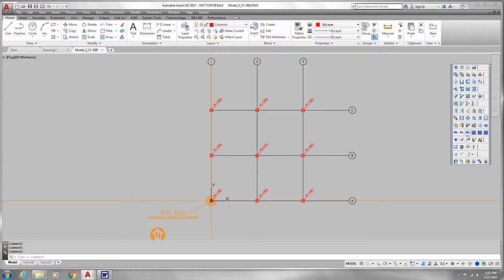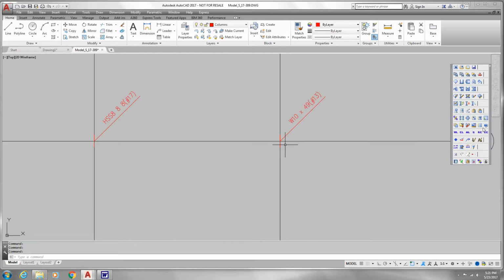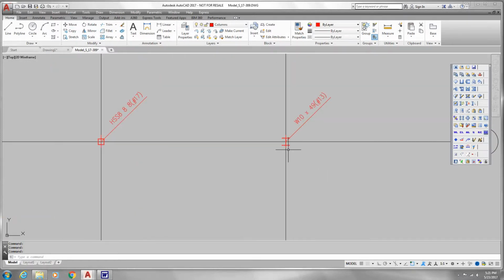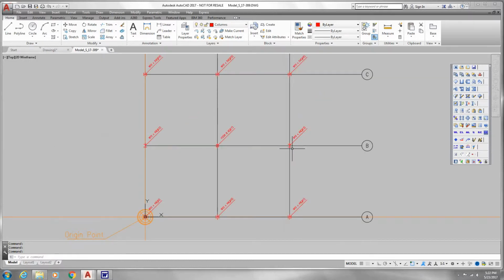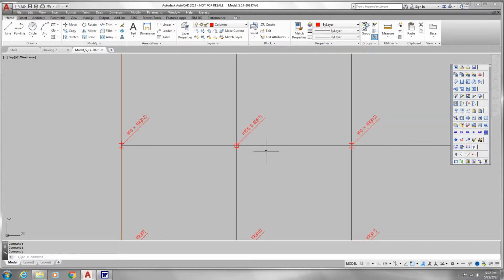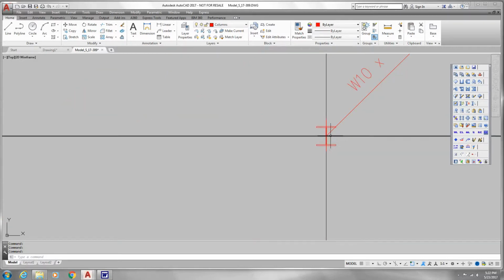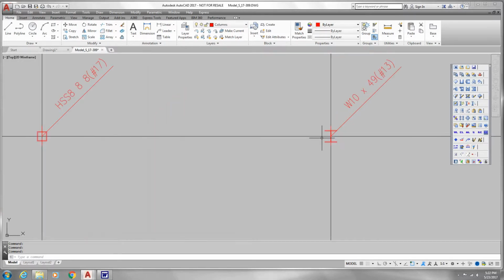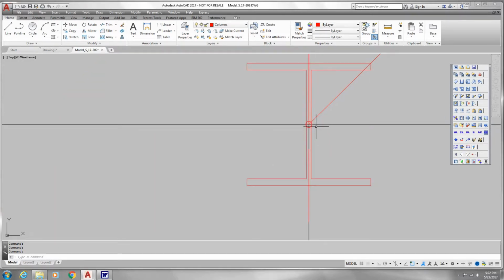The cardinal line and member line have to do with where the actual member is located, and of course the solids. We also have a beam cross section and a column cross section, which, if you have the solids turned off like I do now, you can turn on the column cross section and you just get a 2D representation of the column for orientation purposes. And that's handy when you're modeling in your beams, for instance. If you have the solids turned off, there's not as many places that you can inadvertently pick your points. So you want to be careful to pick your points.